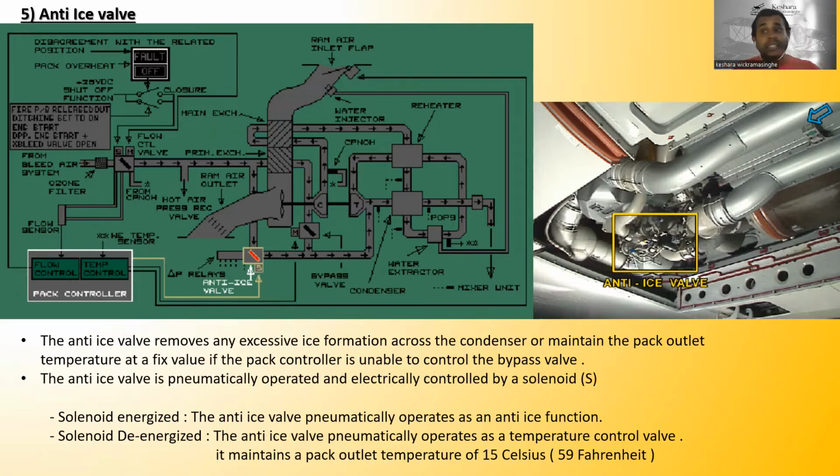All right, and it's control according to a fixed value. Okay, so the anti-ice valve is pneumatically operated and electrically controlled by the solenoid. So remember, the anti-ice valve is pneumatically operated and electrically controlled by using a solenoid. Okay, you can see the solenoid,